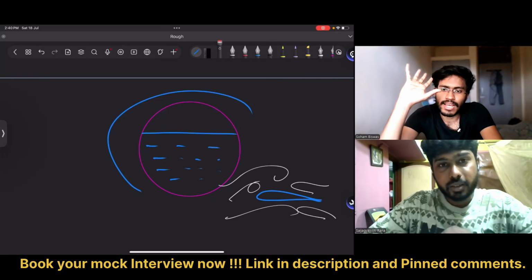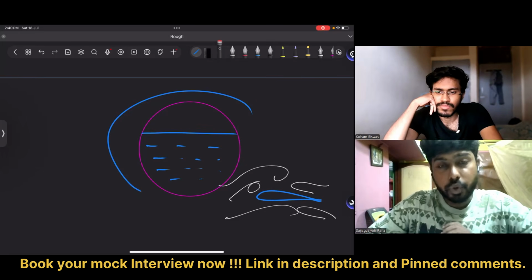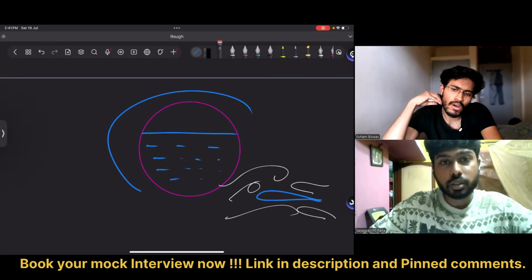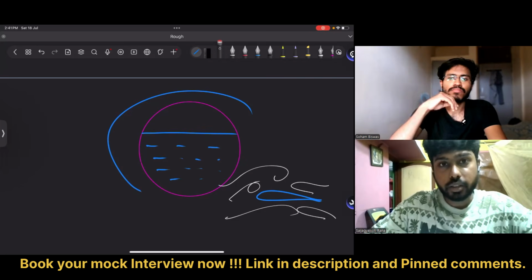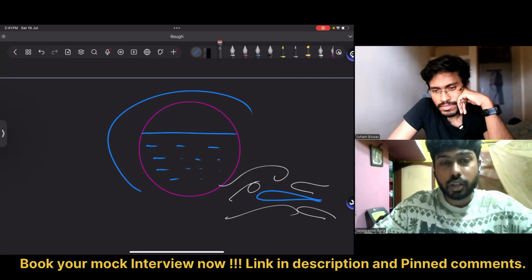Achha, which one is more ductile and which one is more brittle? The 0.9% carbon would be more ductile and 3.4% carbon would be more brittle. Why is it so? Because when carbon composition increases, it occupies a higher amount of interstitial sites. So it makes an intermetallic, cementite, which makes the carbon iron alloy more brittle.